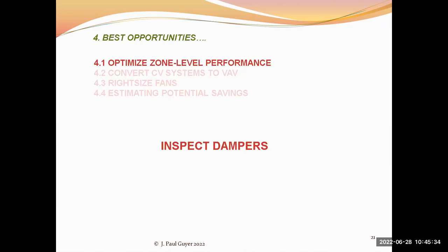And hopefully when the building was designed, there were inspection plates put in place where these dampers were located, so that as the building is operating, the maintenance people can have direct access to all of these dampers and can check and see that they're operating correctly. So inspect dampers.